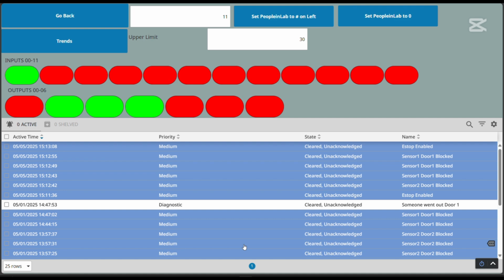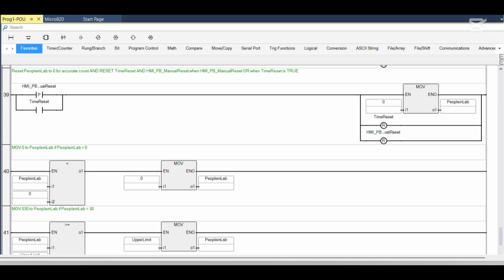I'm going to go over a little bit of the PLC program. As the HMI uses one-shot buttons, meaning it will not just clear the state after the button's been released, it waits for the PLC to reset that state. The program uses a lot of unlatches.